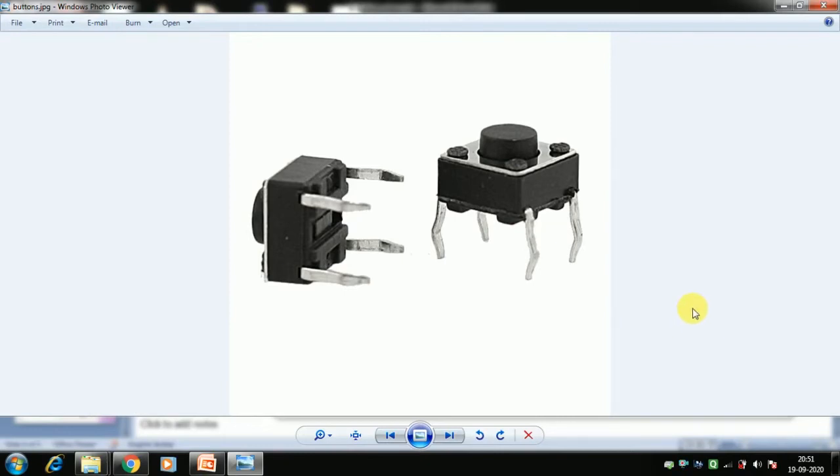So I would like to explain a little about these momentary switches. Momentary switches are called momentary because these are not pushed down and locked. When you push it down, it just momentarily connects the circuit and then it disengages. But even in momentary touching, there are bounces, so very fast it touches and detaches. So that happens. We'll see that when the code runs.